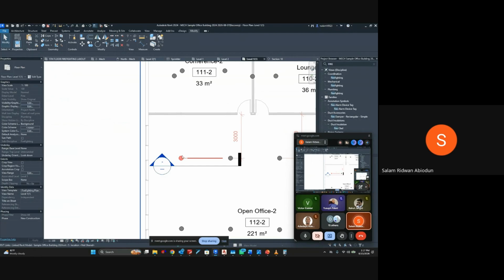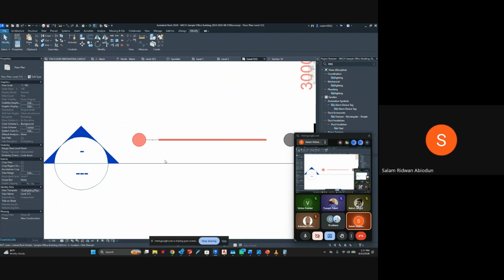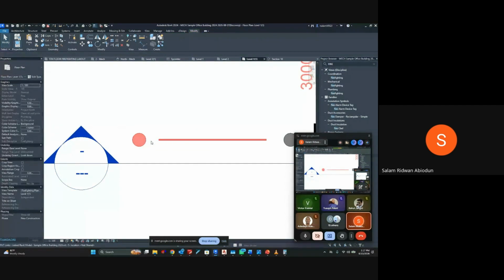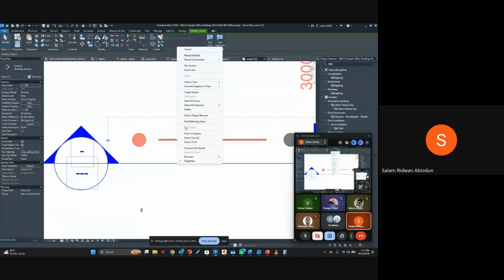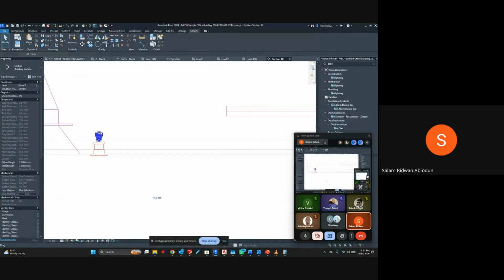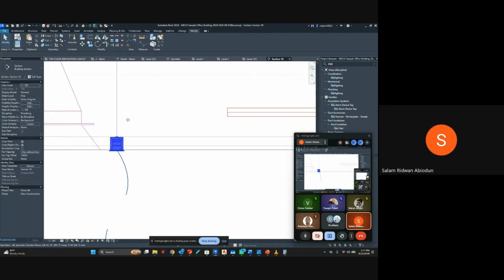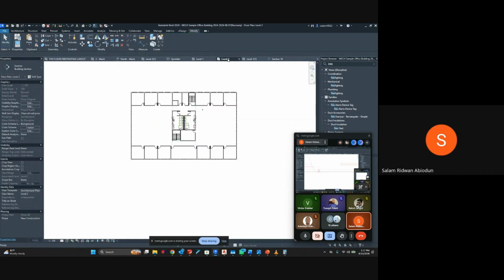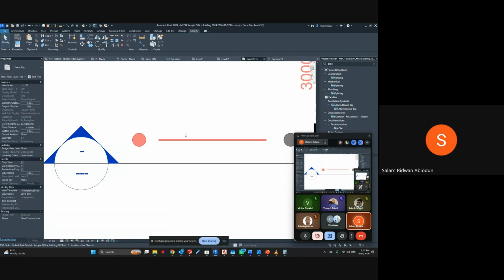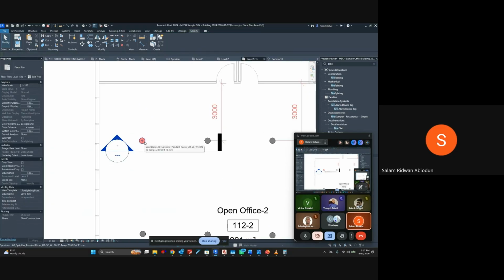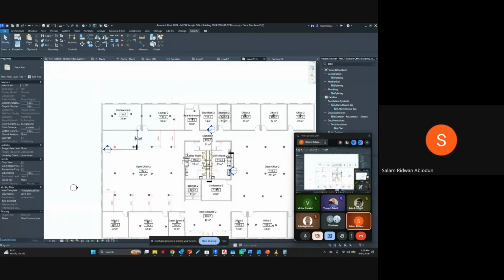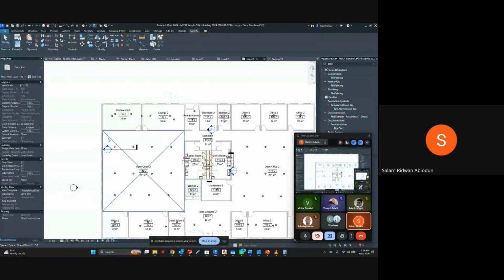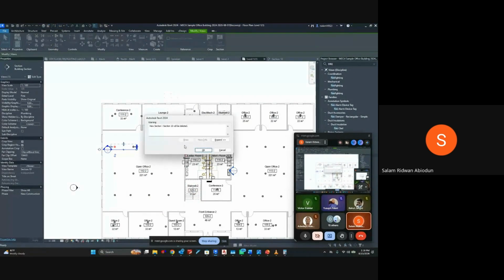Okay, that's that. But to make our work faster, I would like to disconnect this flexible and use pipe. Okay, so you can connect into, look at it. Do we even know that Revit can generate routes for you? Okay, let me tell you. Revit can generate a route for you. Yes, you have to delete all constraints. Delete this one too.